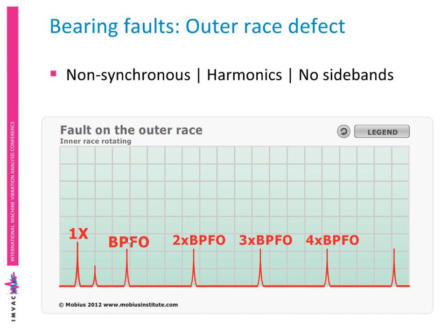So we expect to see a peak at that frequency and twice that frequency, 3 times and 4 times. This is whether we're looking at a classical velocity spectrum or an acceleration spectrum or a spectrum of the enveloped signal itself, be it peak view, shock pulse, or whatever.